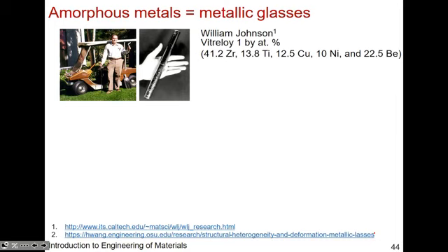Can you manufacture this so that you can sell it? The issue with making bulk metallic glasses is, you can think about it, whenever you have these systems together, they do want to actually crystallize. Maybe the copper and the nickel will find each other and form some crystalline phase that we talked about here. And then the titanium and maybe the zirconium could get together because they're both HCP, and then they'll form a phase. That's what you don't want.